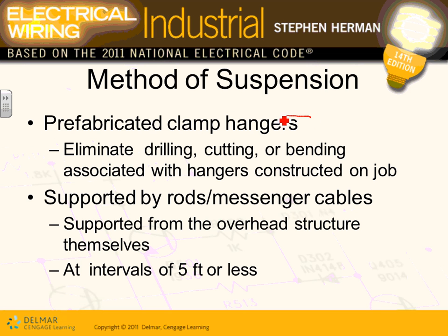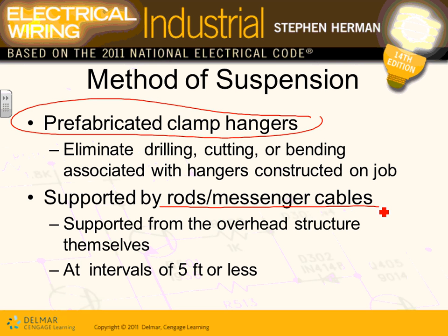So we have prefabricated clamp hangers you can use. They eliminate drilling, cutting, or bending associated with hanging construction on jobs. So there's a lot of prefabricated clamps that you can use. You can support them by rods or messenger cables. You're going to see a picture of these.